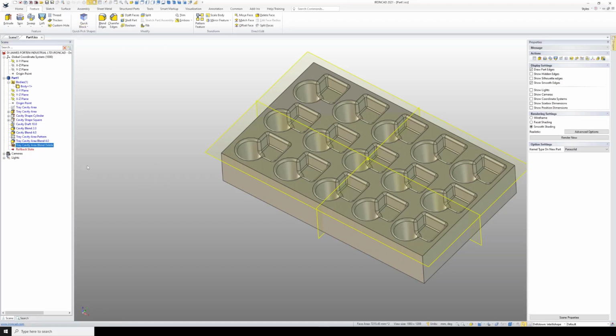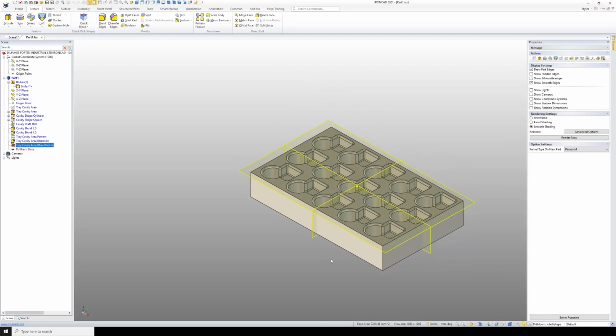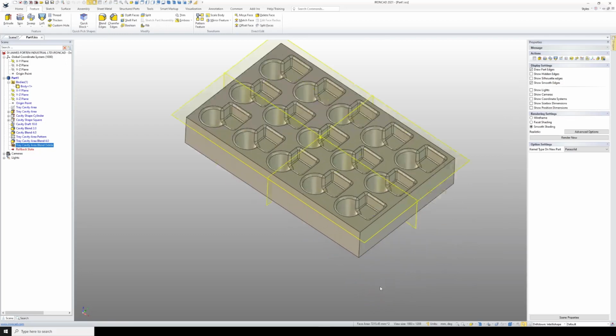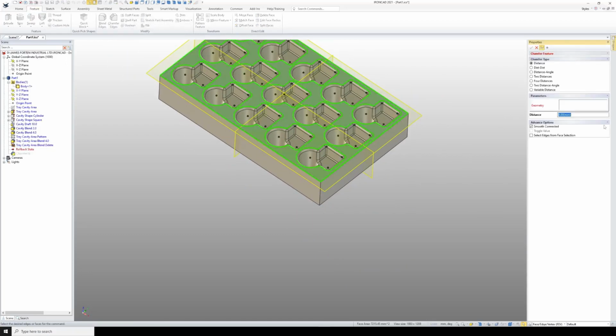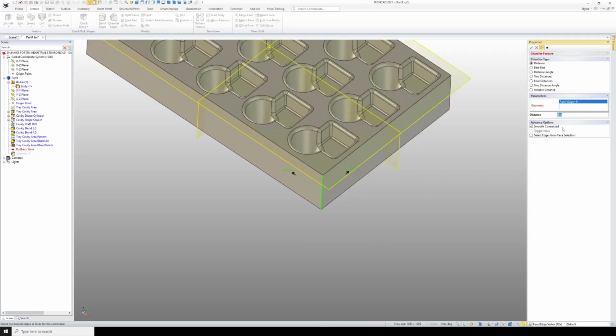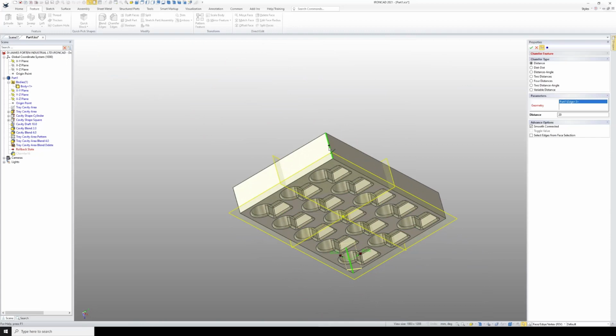All right, tray cavity chamfer. So let's put some extra geometry. We've got a little bit of room at our corners here. So I'm going to put a chamfer here, use our chamfer tool. Select the tool, and we're going to put a distance of 40 millimeters on this edge here. Oh, that's too much. Try 20. There we are. And 20 on this edge as well.